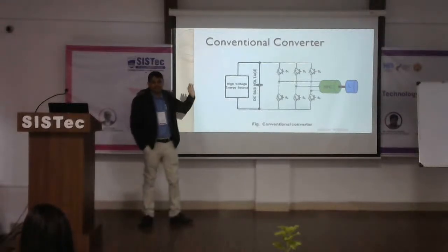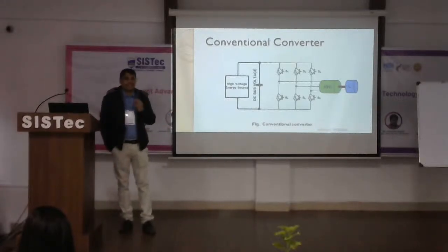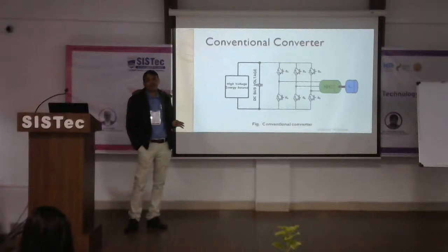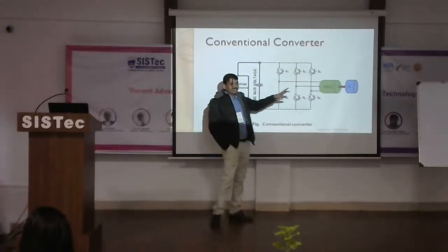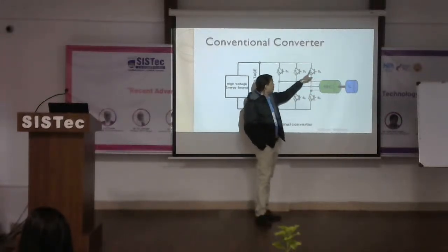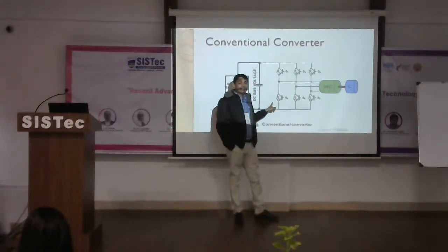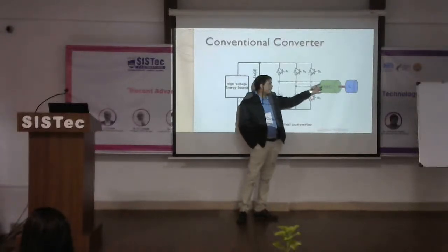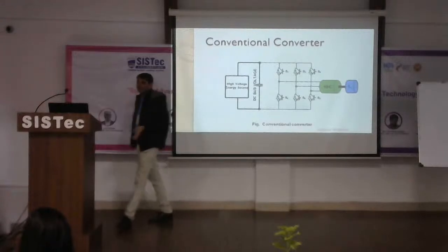So in this system, suppose you are doing 120-degree mode operation or simple 180-degree mode operation, that simply gives constant speed. And if you vary the pulses, meaning all 6 pulses, as per your requirement, the speed will vary. And when this motor works as a generator, in that time we are not providing the pulse. You can see these anti-parallel diodes are there. These diodes work as a rectifier, so that AC power will be fed back to the battery. So that is the conventional system.